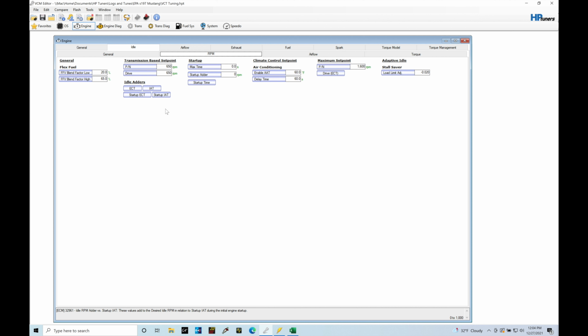The airflow will drive up or down the amount of torque we produce in idle conditions pretty drastically. In this case, with a Gen 1 Ford Coyote PCM, we have drive-by-wire throttle control. We don't have an idle control motor that allows essentially a controlled vacuum leak externally through a solenoid. We're using the drive-by-wire electronic throttle plate movement to influence the amount of airflow coming into the engine under idle conditions. We let more air in, we'll find we drive up the engine's torque production and we'll have a higher idle speed. If we reduce the throttle plate movement, then we'll have less airflow, less torque, and we'll drive down the engine's idle speed.